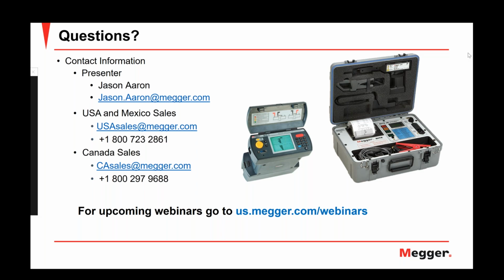So, as was shown in the presentation, the method is injecting a current, or having a current circulating through the cell, and measuring a voltage drop, and that allows you to measure an impedance. In that sense, you could say that you can apply this to all types of batteries. However, the important thing here is how to analyze the results. So it's not, as Jason indicated at the beginning, an absolute value that you're looking for.